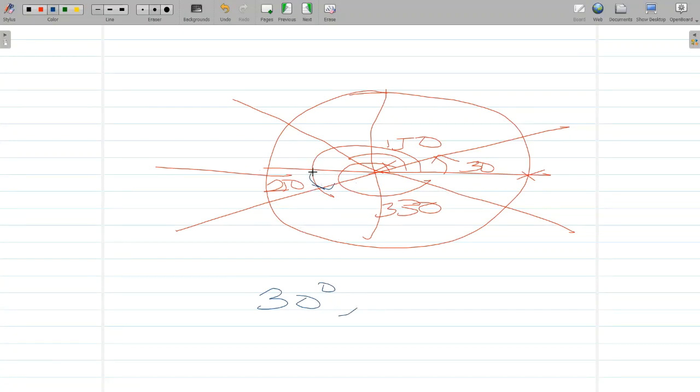And the 330-degree point is nothing but 330 minus 180, which is 150 degrees. So from my front stagnation point, if I go 150 degrees, I'm going to reach that stagnation point. If I go 30 degrees, I'm going to reach the other one.